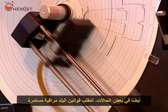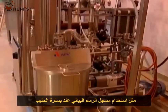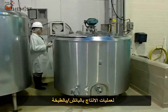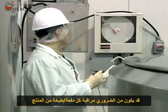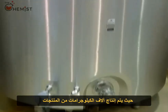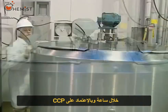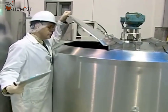Also, in some cases, regulations require continuous monitoring, such as using a chart recorder when pasteurizing milk. For batch processes, it may be necessary to monitor every batch of product or second batch in large volume production, where thousands of kilograms of products are produced in an hour, and depending on the CCP, it may be necessary to monitor every 5 minutes.